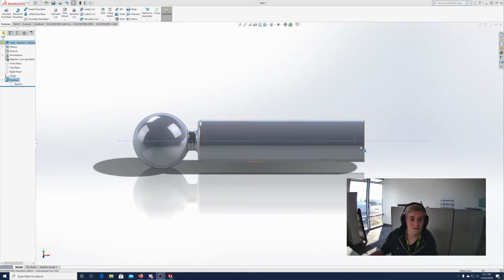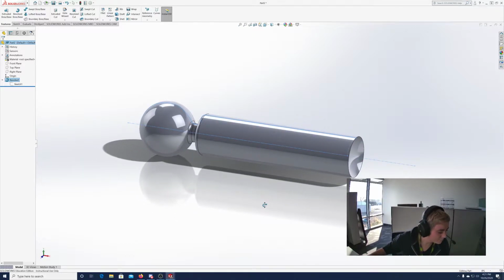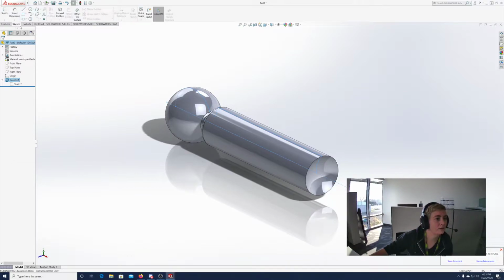So we're going to continue with step 3 on page 5-4, sketching the open-end profile. So we're going to do a new sketch. I'm going to put it in the top plane. So you're going to click top plane over here on the left.